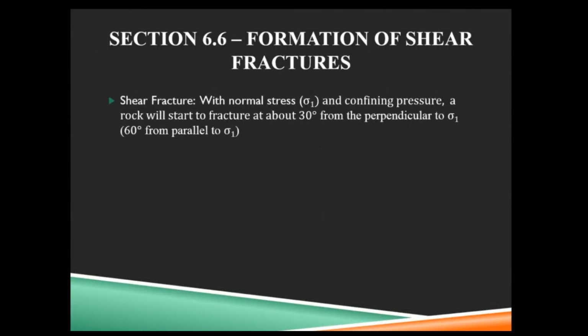Now, formation of shear fractures. We've got a normal stress. Sigma 1 is our big normal stress, normal being perpendicular, and perpendicular to the confining pressure, our sigma 3, much lesser than sigma 1. The rock is going to start to fracture about 30 degrees from the perpendicular to sigma 1.